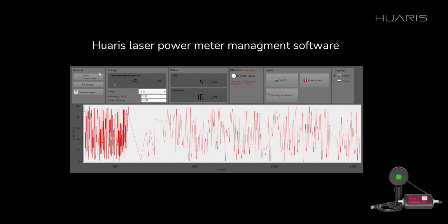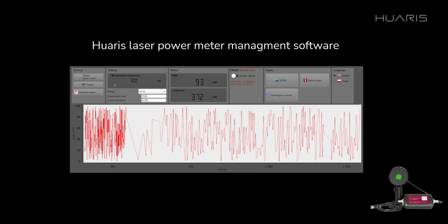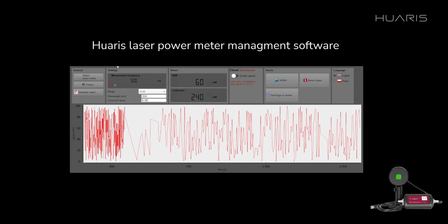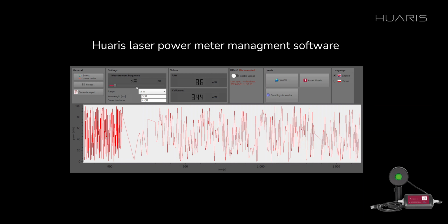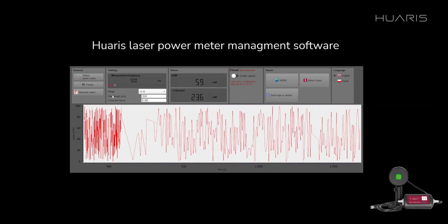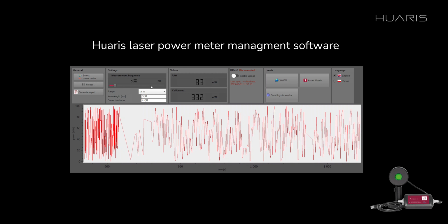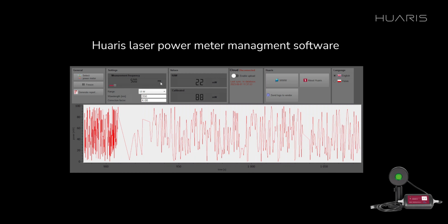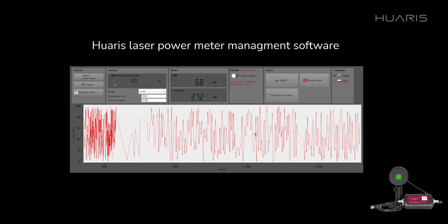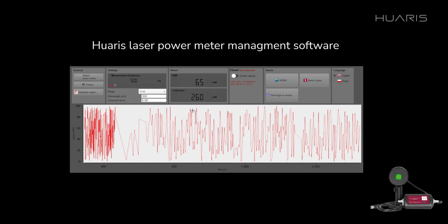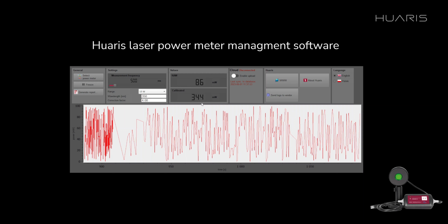In the second section called Settings, you can change a few things. First of all, you can change the measurement frequency. So essentially, you can modify how frequently the power will be measured. Here I've set 500 milliseconds, so essentially half a second. And this means that every half a second another value will be displayed here in the following section.